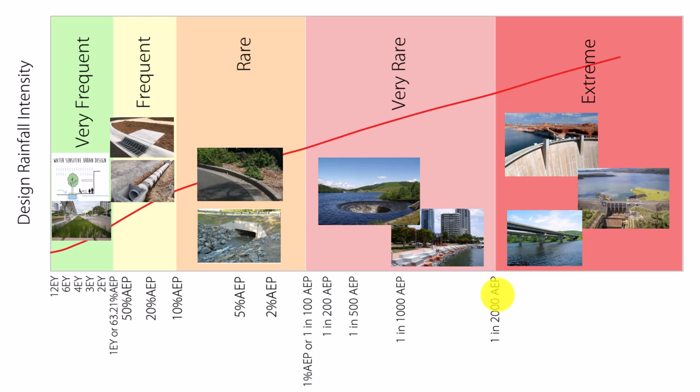And to summarize the terminologies adopted here in Australia in particular, according to ARR, Australian Rainfall and Runoff, I want to show you this graph, which shows the preferred terminology on the x-axis and the design rainfall intensity. So we can see that it increases as we work with more important and larger infrastructure. We start with very frequent storms for designs that only help reduce runoff by about 5%. And then we move to minor drainage systems, major drainage systems, reservoirs, waterways, large reservoirs, and bridges. And here is the terminology preferred according to ARR.